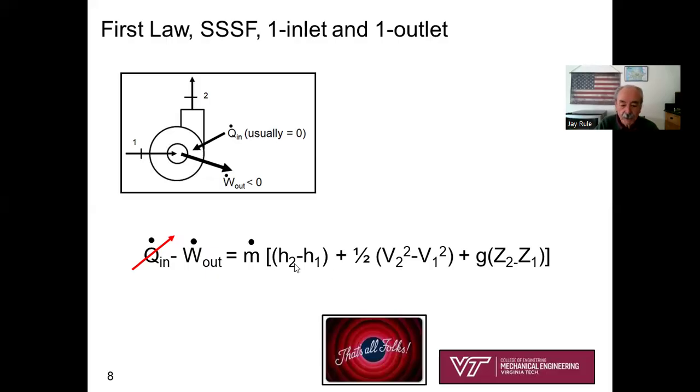And then h2 minus h1, of course, what you're looking for here is you must know T2 and T1 in order to look up the property enthalpy as saturated liquid at the temperature of the liquid. And of course, you're always trying to find the output power, or in other words, you get a negative number, the power required to drive the pump. So that's the common engineering need when you're analyzing pumps: how much power do I need? What size electric motor do I need to select to drive this pump? Do I need 2 horsepower or do I need 20 horsepower, or similar in kilowatts? So you get the idea.